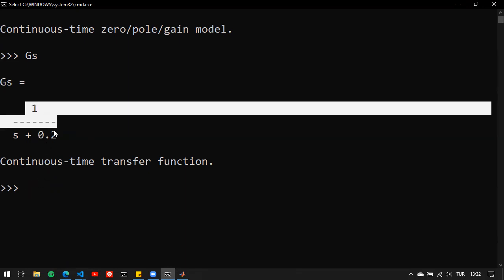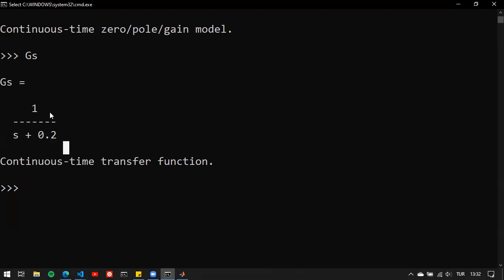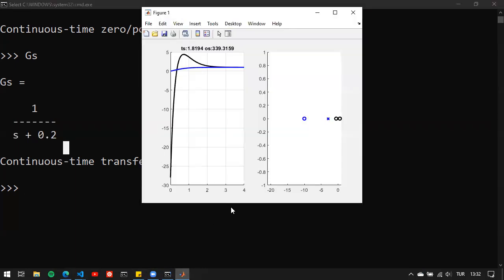And the best thing about this is that you can just design a PID controller, aim for a PID controller. And if it's not working well, you can just change your structure to a PI-PD controller, because you are just concerned with the poles of the system. In this case, we achieved the best possible set of poles in the closed loop. The only problem was that we had some zeros that were troubling us. One of them was on the right half plane, one of them was on the left half plane. Therefore, using the structure, we got rid of those adverse effects of the zeros.